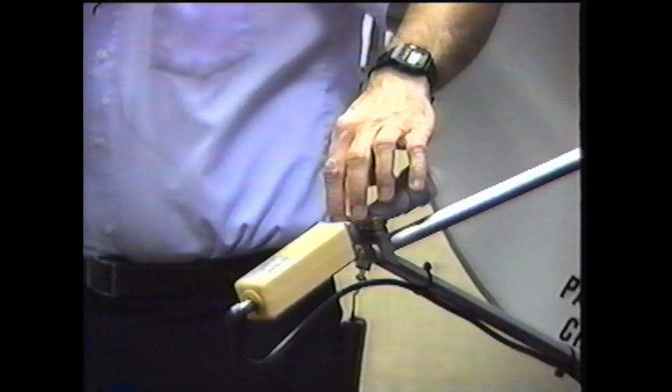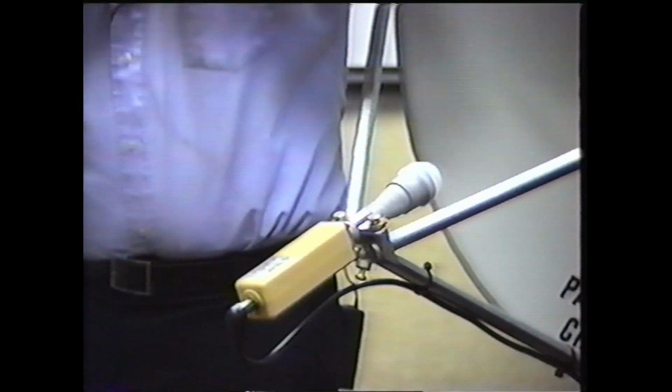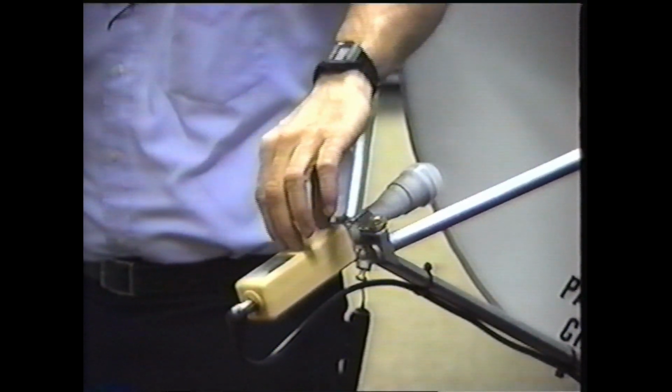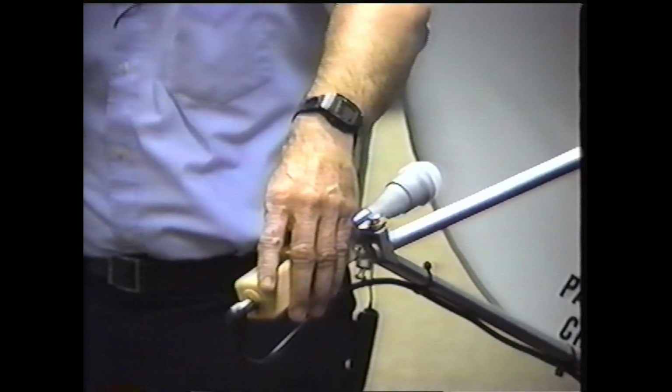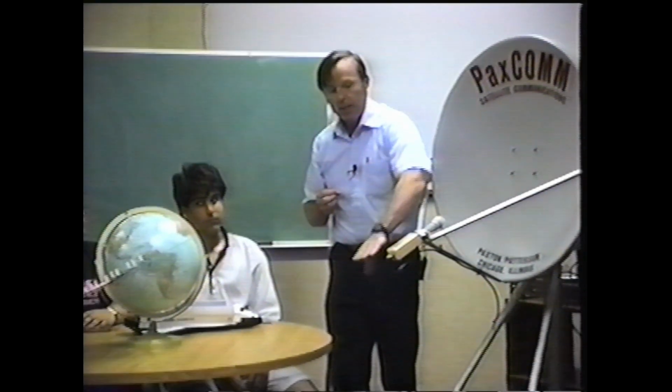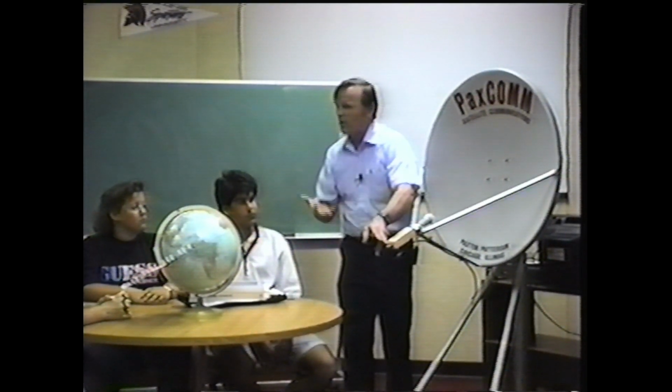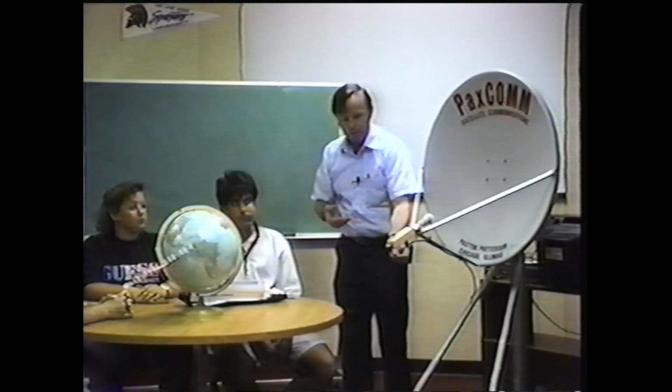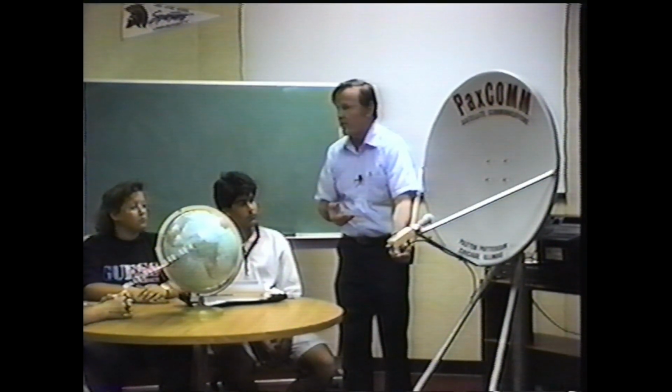And the antenna is only about 1/4 of an inch. It takes the signal from the antenna and processes it in this box, which is called a low noise block down converter. It lowers the signal in frequency, or lowers the channel, to a point that it can be transmitted in this kind of cable.